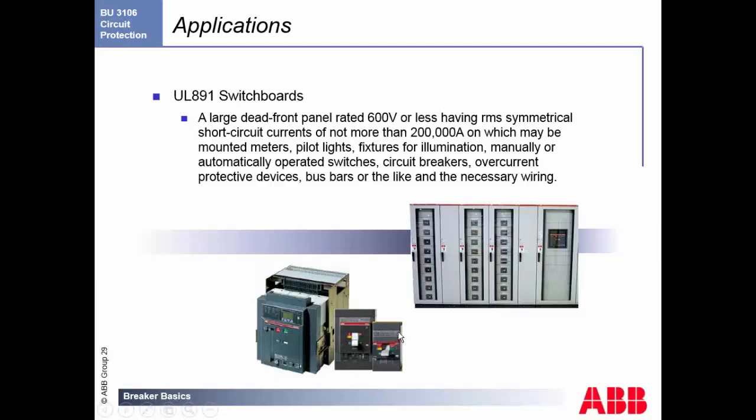This allows you, if you do the selective coordination and your studies properly, to make sure that the breaker closest to the equipment pops first, reducing downtime, reducing cost, and reducing maintenance. This is used in just about every application I can think of, where you have your main breaker here. That's this Emax, which is a huge breaker that's bringing in all the power. We break it out into feeder breakers, and then eventually down to your actual branch breakers.